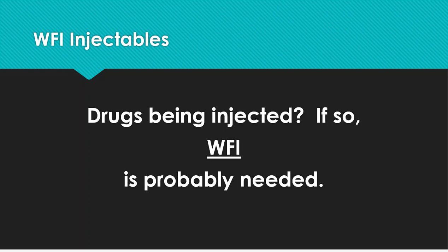If they are not meant to be injected into someone's bloodstream, then there's a chance that we can get away with a lower quality water. It doesn't have to be water for injection, but it still has to be very high grade. It still has to be very pure. So when I say that, I say it very loosely, because we still want those very strict water quality measures in place. But we're not necessarily too worried about the pyrogens. Only when we inject them are we worried about those problematic little children from those bacteria mommies and daddies.